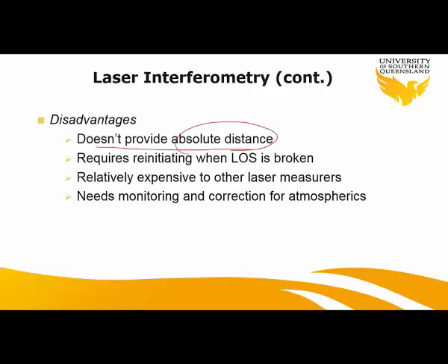This is not a good system at all, because once your line of sight is broken, you have to restart the system, reinitializing for the first distance. Do you remember I told you we always start from one point and then measure the relative distance? So you have to restart the whole system and start over. So this is not a very good choice for busy environments like construction sites. This is not a good system at all.